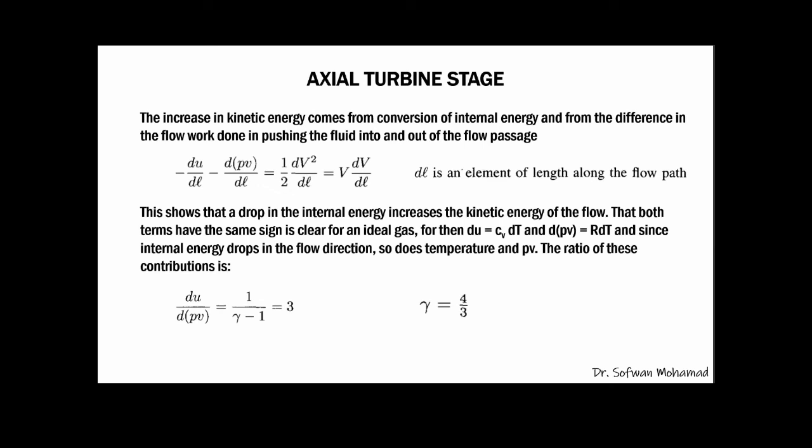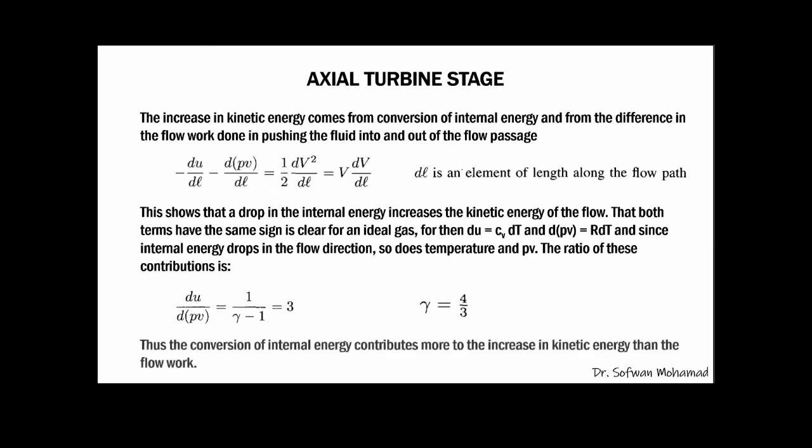This is quite constant for almost all cases of reaction turbines. Thus the conversion of internal energy contributes more to the increase in kinetic energy than the flow work.